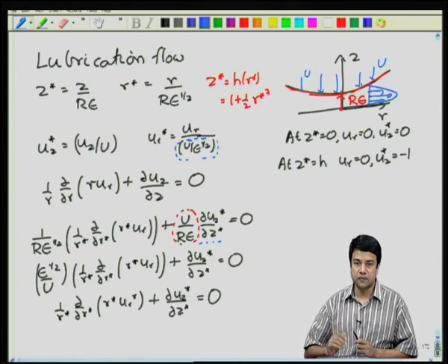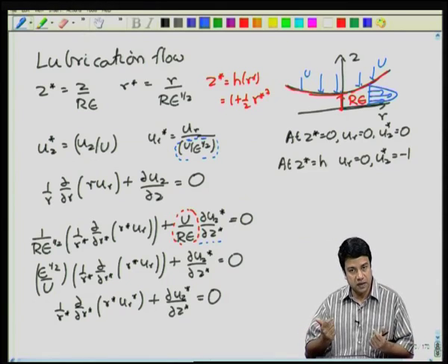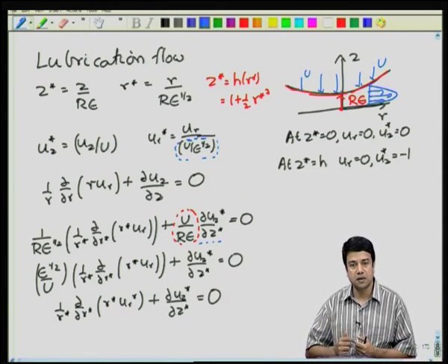Okay. So, therefore, the fact that the sphere is coming down, all the fluid that is below the sphere has to rush out of that small gap, that is generating a velocity which is much larger than the velocity with which the sphere is coming down.